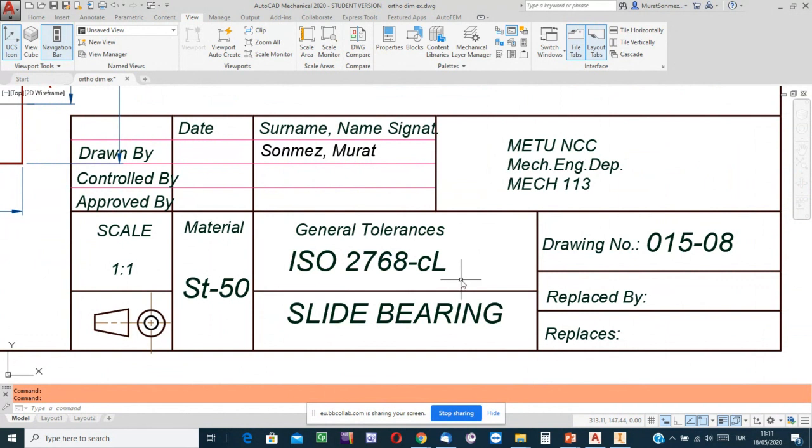Saying geometrical tolerance, we mean in short the allowance to control the form of the features: flatness of feature, perpendicularity of feature, parallelism, runout, circularity, cylindricity, etc. These are geometrical characteristics, and to control the form of the features, we use the geometrical tolerance technique. It is the subject of MEC 114.